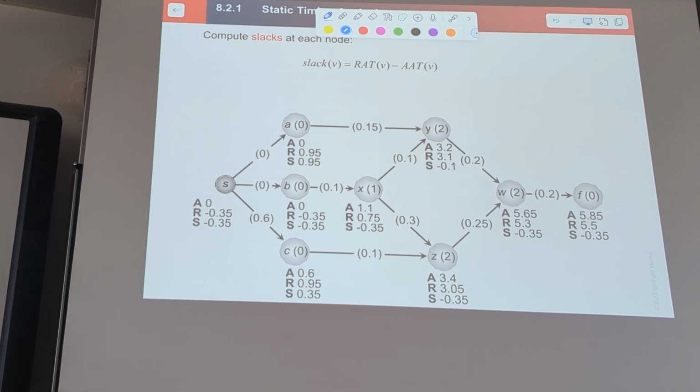from you take the gate delays, you take the wire delays, you put that in a simulator and you simulate your function, and then you have checkers which check whether you have setup and hold violations at all flip-flops, which give an alarm if there is a violation, and if your delay is so bad that you end up 1 clock later, there will be a functional difference, and hereby you could check whether your timing is okay. That's the methodology from like the 70s or 80s, where you tried to back annotate all your timings, run the simulation, and see whether it's still working.